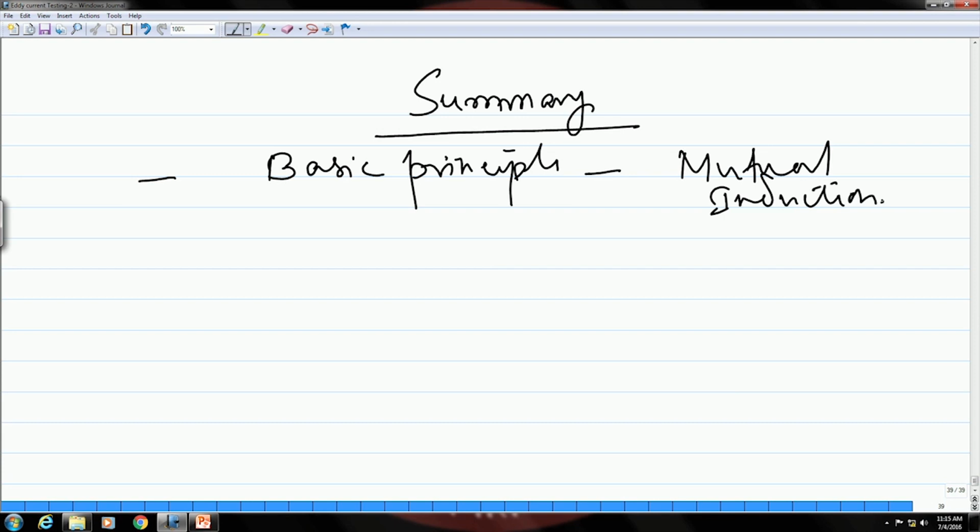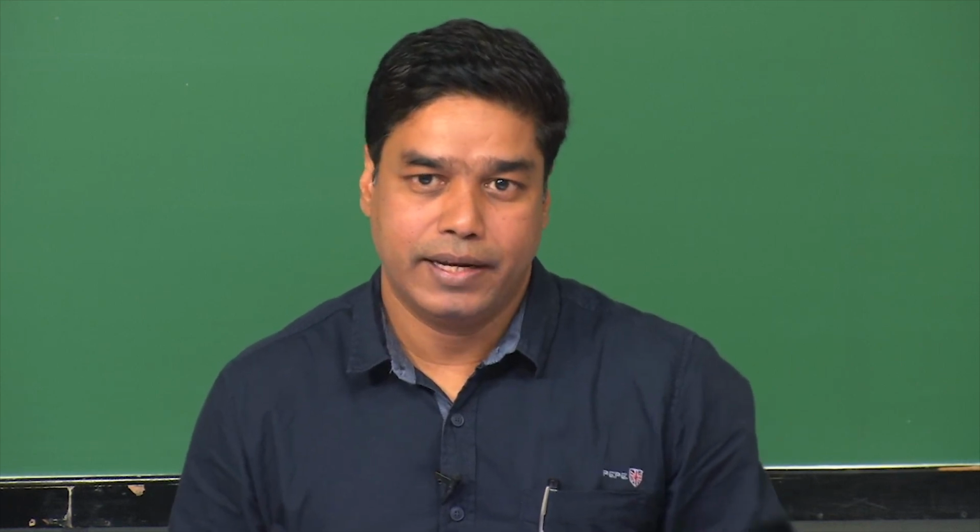And a change in the impedance of the primary coil due to the presence of surface defects on the sample, which changes the eddy current which is flowing on the surface of the sample. Okay.